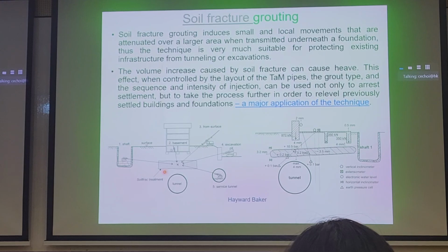Some ways to do that is you can excavate a shaft, and then you can put a drilling rig and carry out horizontal drilling to the location underneath the building. If there are existing service tunnels, for other utilities for example, then you can leverage these service tunnels, put the rig in, also carry out horizontal drilling, and then you have these two drill holes to insert the grout.